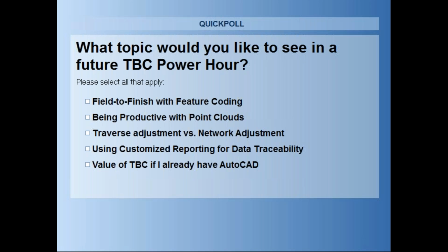What else do we have here? There's a lot of questions. I'm sifting through all these. Mark asked, can we label ground or grid distances when labeling? Right now you cannot choose between ground or grid distances, which is unfortunate. Once again, this is another thing that we've noted, as a lot of cadastral surveyors want to have the option of labeling at ground and grid distances. If you use the local site settings, though, this essentially aligns your project with the ground and grid distances, so you can use the local site settings to essentially help with your labeling.